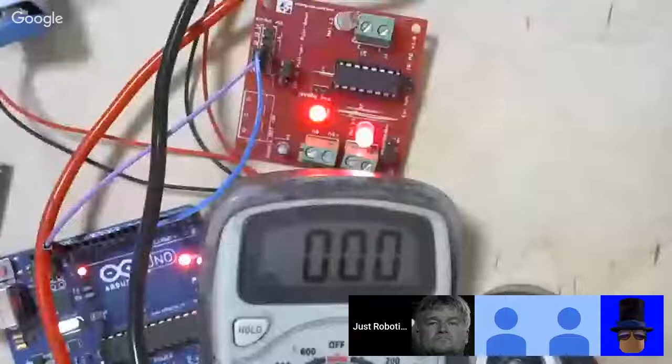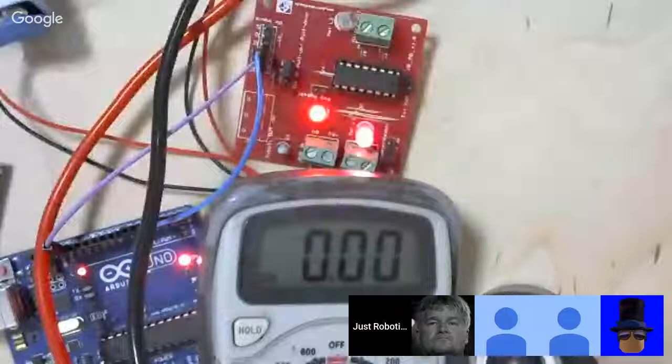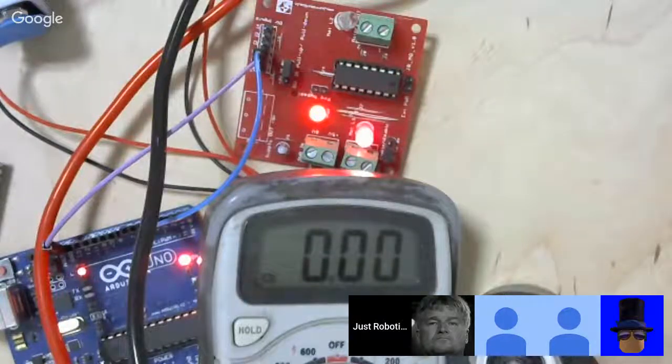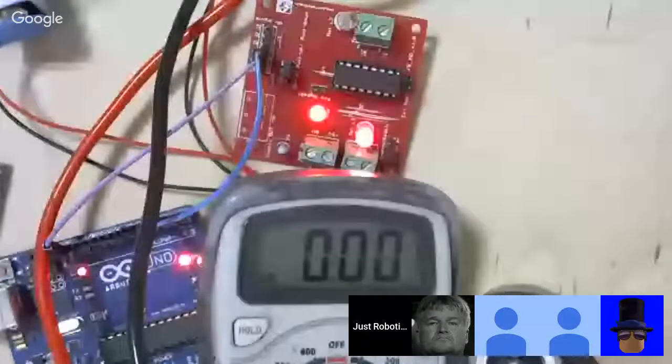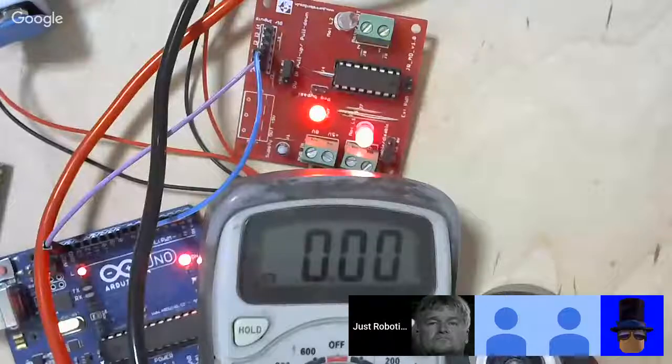Whatever you're doing with the program right now, you can also include analogWrite instead of digitalWrite and see the difference that it makes in terms of speed control. So this is very important, especially when you have robots where the RPM of both the motors are not the same.